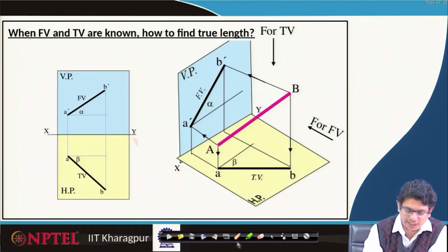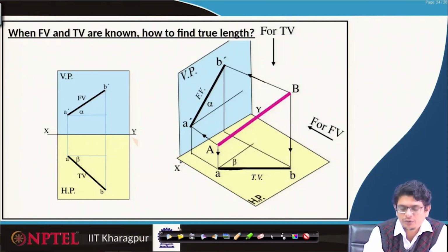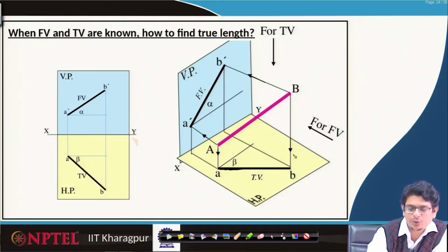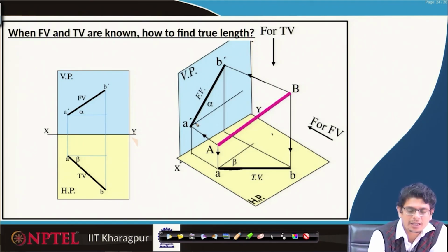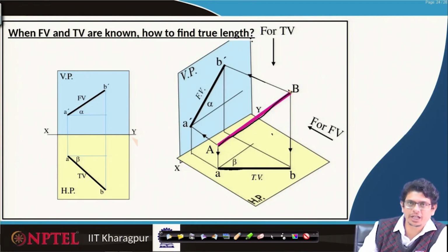When we have this projected line in 3D, let us look at this. We already have AB thing. What we want to do is project that one, rotate it by horizontal direction. That means, this length we want to really rotate it, so that we will be in a position to mark a point somewhere there. Then transfer it all the way up. Then extend this line, so that we will be in a position to construct that true line. Then rotate it back. Then we will be in a position to get that AB line. This is the way we construct it.